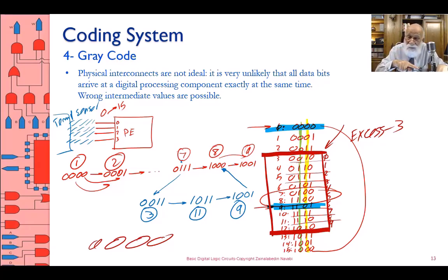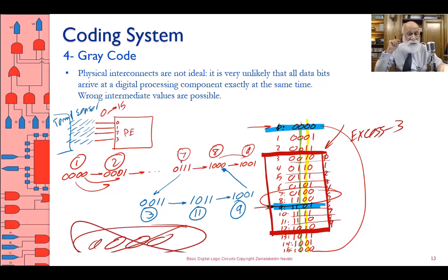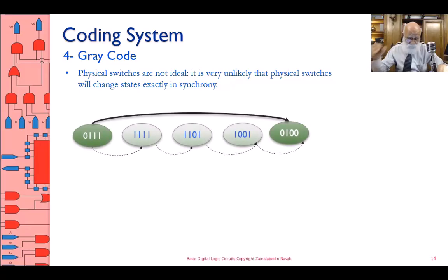It's maybe a signed number, maybe a completely different representation of number, or maybe it's a gray code, maybe it's an XS3 system. If I tell you 0000 and tell you this is an XS3 system, then you say no, it cannot, because XS3 system goes between 0010 all the way to 1010, and no 0000 exists in the XS3 system.